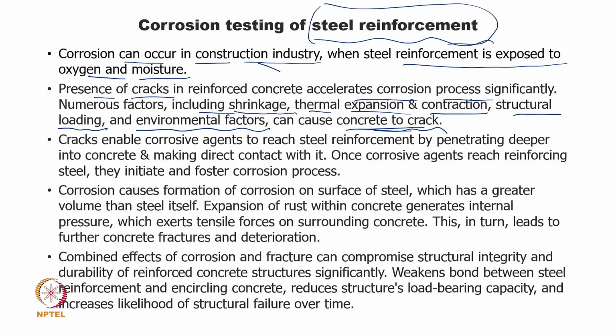Now, once the cracks are formed, the cracks will enable corrosion agents to reach the steel reinforcement element by penetrating deeper into the concrete and making direct contact with the steel surface. Once the corrosion agent reaches the reinforced steel, it initiates and fosters the corrosion process.